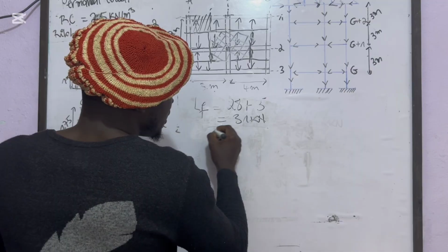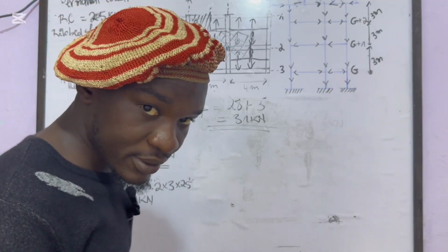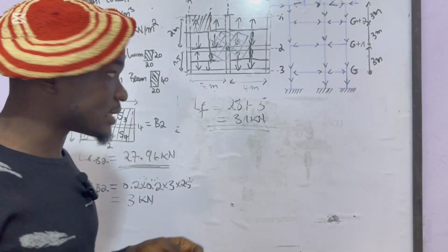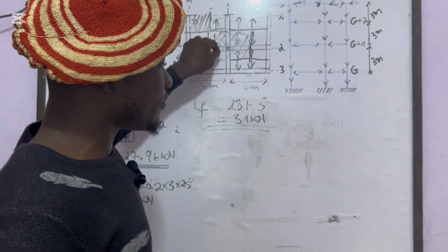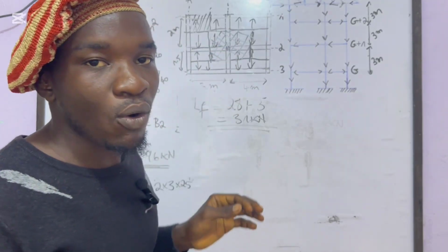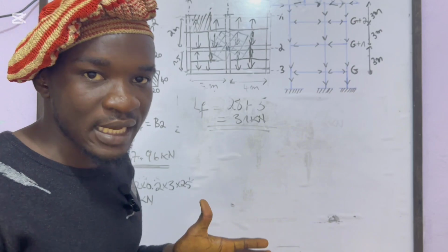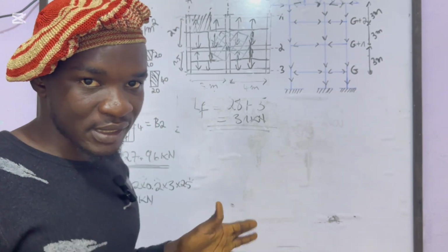Normally, if you are to design, this should be the load we consider, but there's still one detail: we have to consider the surroundings of that column to see whether it is near an external column or not. And if yes, how many external columns is it near to?